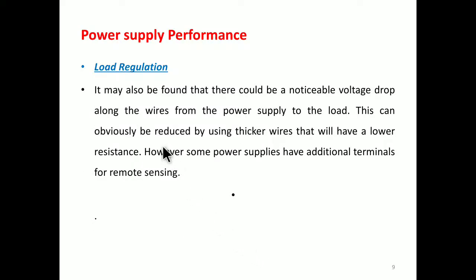It may be found that there could be a noticeable voltage drop along the wires from the power supply to the load. This can obviously be reduced by using thicker wires. If you use thicker wires, we can go with smooth operation.